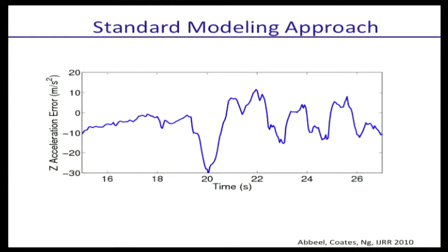Minus 10 meters per second squared, that's the acceleration you get from gravity. So we're off by the same force as gravity has, up to actually 3 times gravity, how much the dynamics model is wrong in predicting what's going to happen. So you can now understand why it went so wrong in that first video. If you can't anticipate that gravity is 3 times, 4 times, in fact, because gravity is there and then there's 3 times extra on top of it, you can't predict that, then you're not going to do the right thing with your model-based controller.